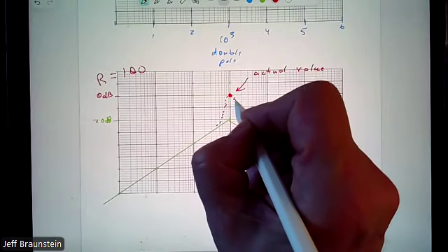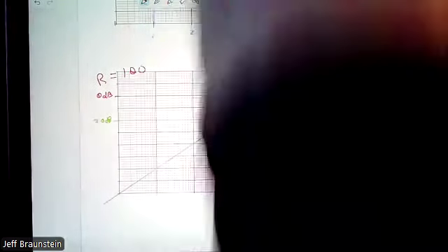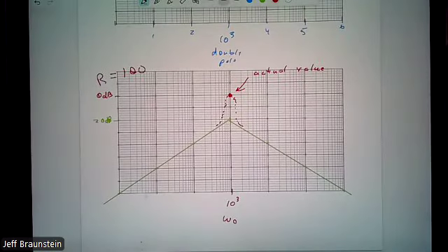Here is our actual Bode plot. You can go simulate this. There's my actual dB Bode plot, the red dashed line, and then conversion to an asymptote to my green line. What is this? This is a narrow bandpass filter. If you want to tune in at just a given frequency, this is what you built. This is very real, historically.